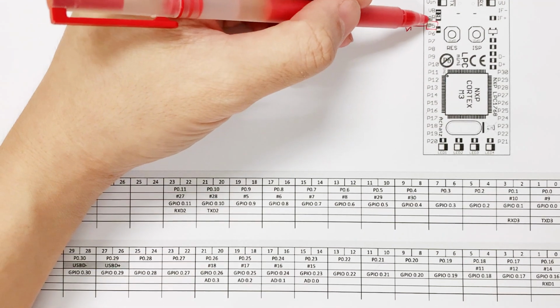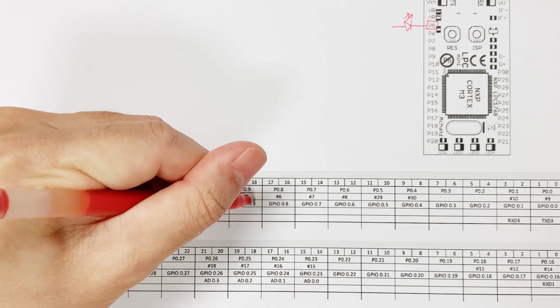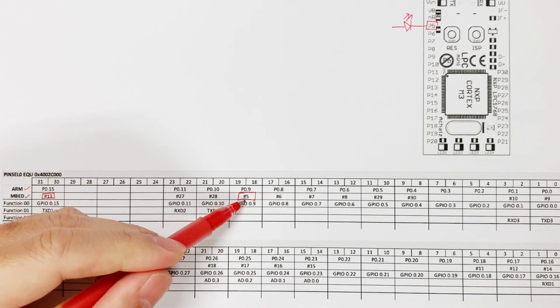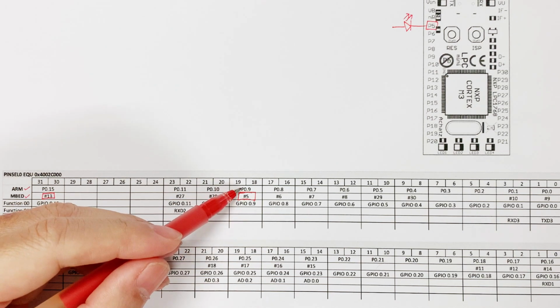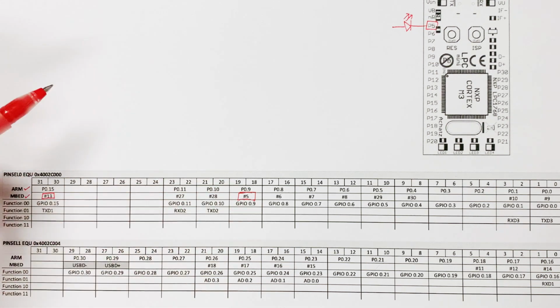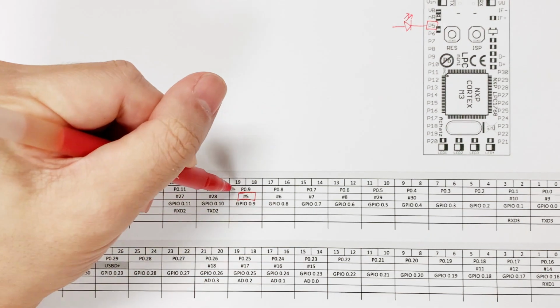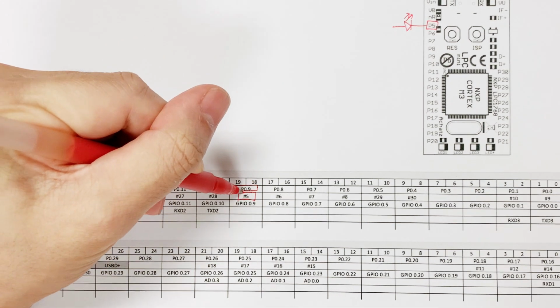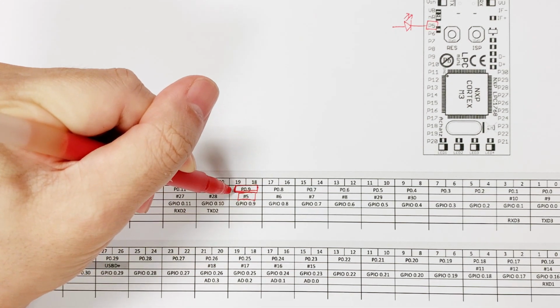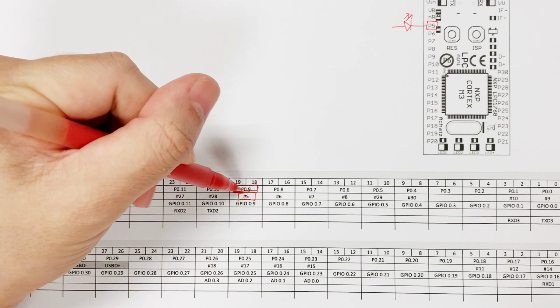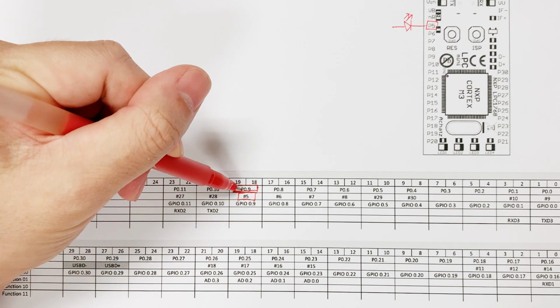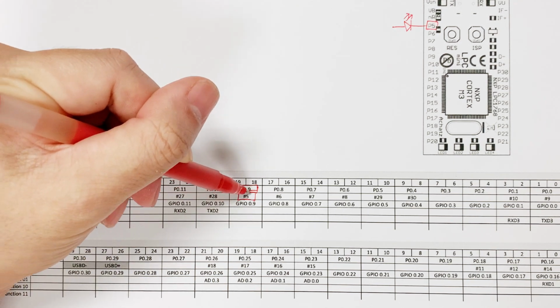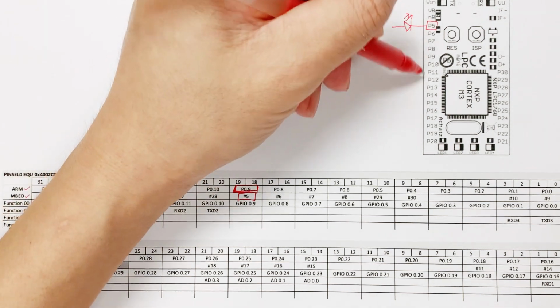Take for example pin 5. If you refer to the table, pin number 5 is actually connected to the ARM microcontroller port 0.9. It's important for us to know the port number and the related pin in the microcontroller, because when we are doing assembly language, we are using port 0.9 instead of P5 as provided by the mbed module.